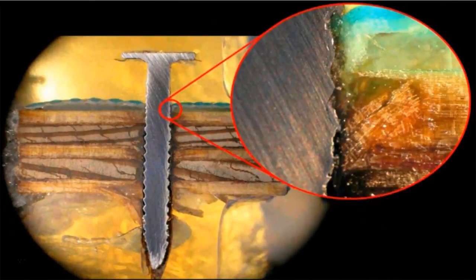Seen in the cross-section under a microscope, we can see how this sealing process works. The nail does not make a physical hole through the membrane, but rather separates the microscopic fibres around the fixing. These fibres then clench tight around the shank of the nail, forming an effective seal around the fixing, provided the nail remains in place.